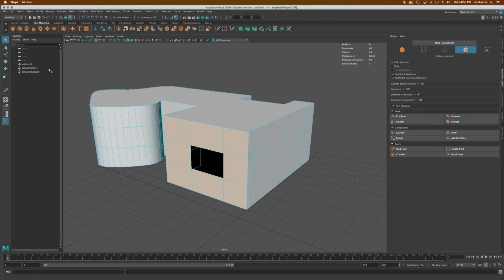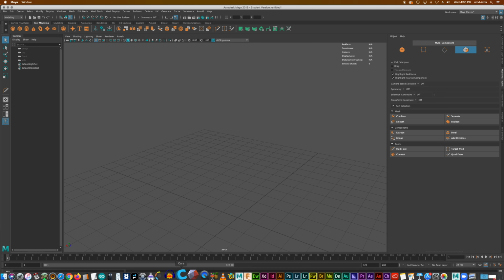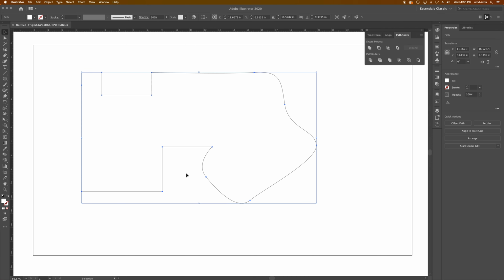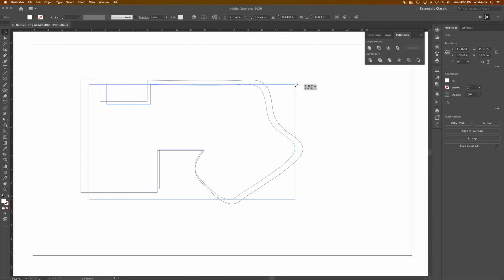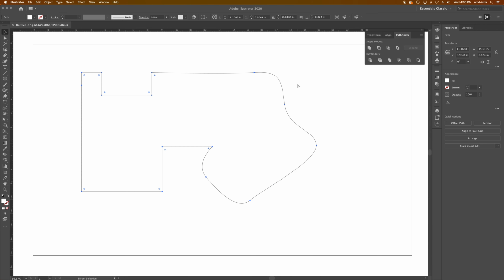If I go ahead and just delete this whole object, I could have done a little more prep in Illustrator. So I have this object, right? I could duplicate it. And actually, in Illustrator, you want to do copy and paste in place. That's Command-Shift-V, or up here, Edit, Paste in Place. Duplicate doesn't quite work the same way. And if I hold Option and drag it in, it will scale it.